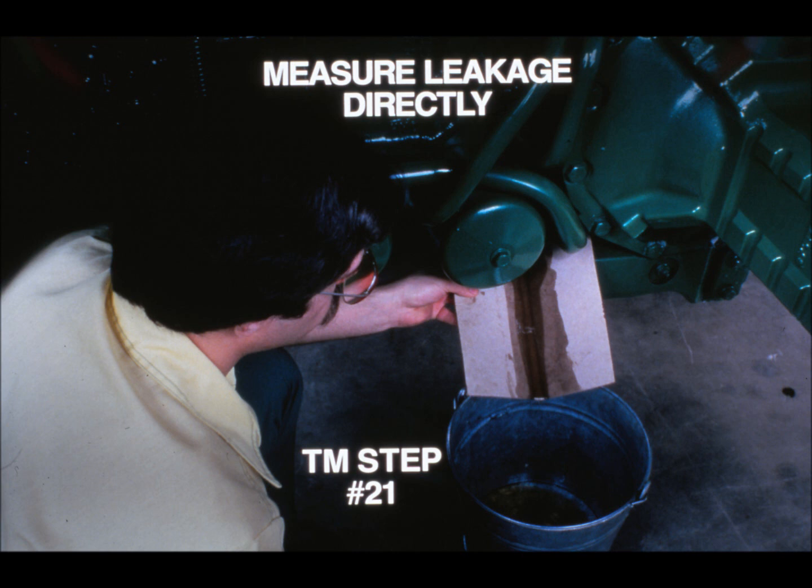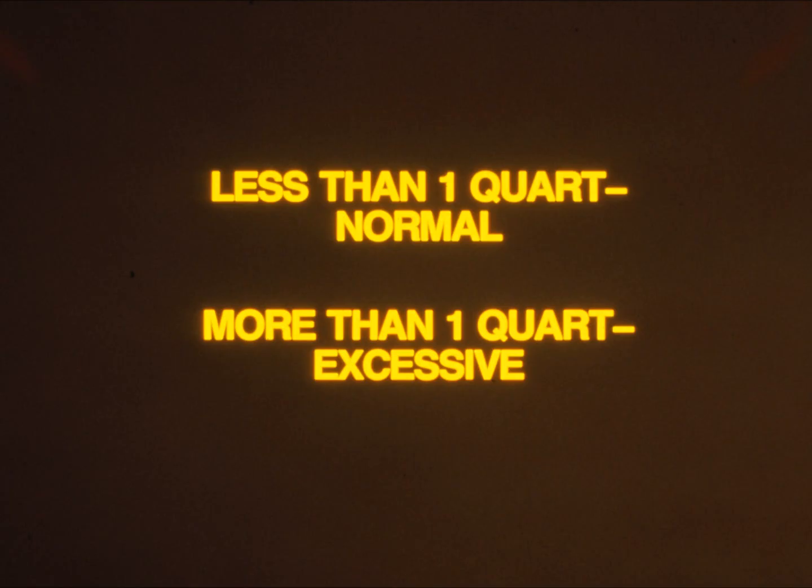Run the engine at 1,000 RPM and let the oil flow for 1 minute. Measure the oil in the bucket. If the amount is less than 1 quart, leakage is normal. Go on to the next diagnostic step, number 23. If the amount is more than 1 quart, there's an excessive leak in the rock shaft or SCVs.